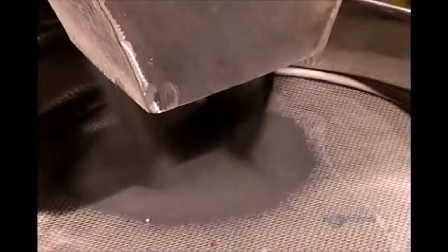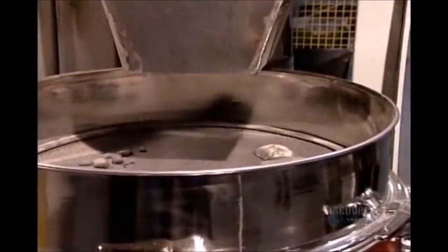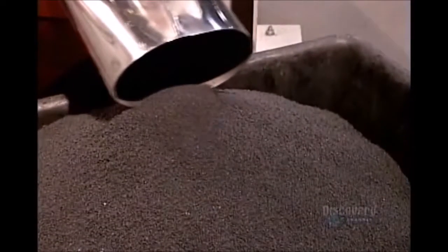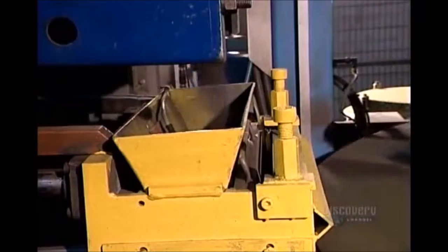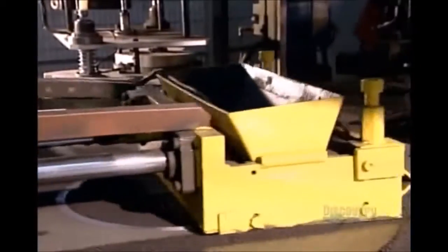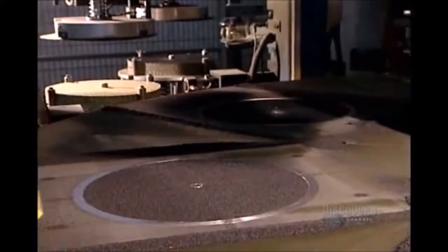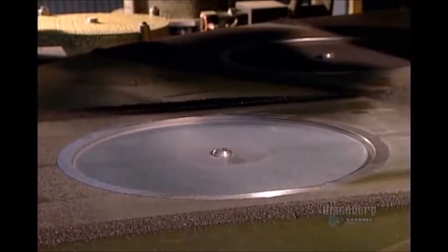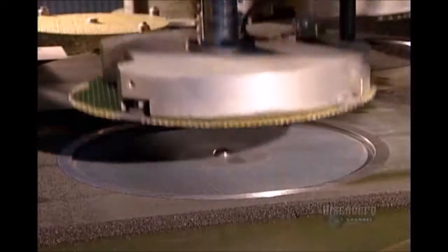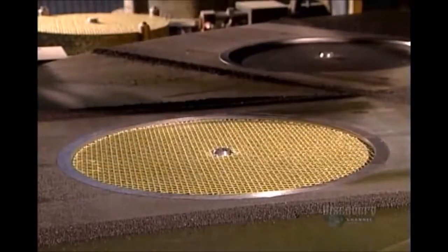This process generally works by having the grinding wheel composed of abrasive particles that are bonded into the shape of a wheel. When the wheel comes into contact with the workpiece, it acts as a cutting edge that removes material in the form of tiny chips. As it removes workpiece material, worn abrasive material from the wheel becomes dislodged. This allows unworn abrasive particles to perform cutting, allowing the wheel to efficiently remove material throughout its hours of operation.